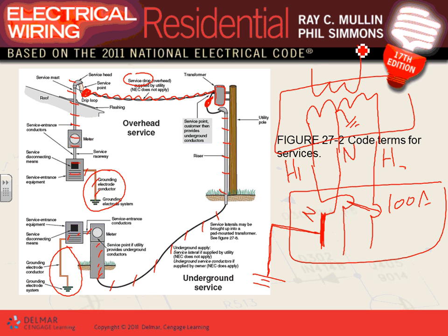Any questions? So Derek, my friend, when you bring your cable in here, the first thing you must land it on is, this circuit breaker is called the service disconnect. You have to have a circuit breaker or a fused disconnect so you can land your cables on the service disconnect. That's a requirement by code. So for example, can you have a main lugs only? What's a main lugs only? A panel that does not have a circuit breaker ahead of it. As a service panel, no, you can't. It has to have a main circuit breaker, or it has to have a circuit breaker ahead of it. Any comments, guys? Any questions?